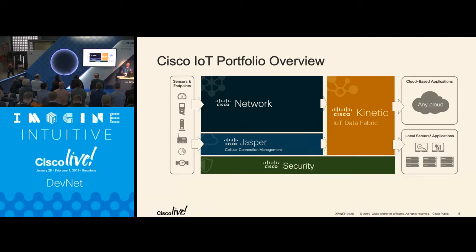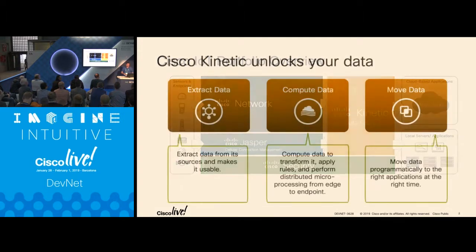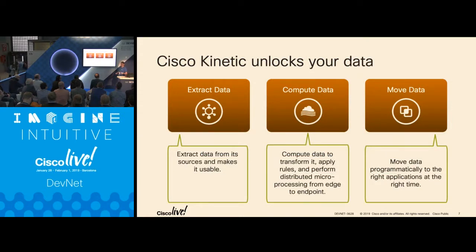If you have sensors that do not talk any protocol, like for example a door contact, it's open or closed, then you have to plug this one into a gateway that will transform that into something we can understand, like a Modbus TCP gateway. If you come by the Cisco booth, we have that. Okay, so let's go back here.